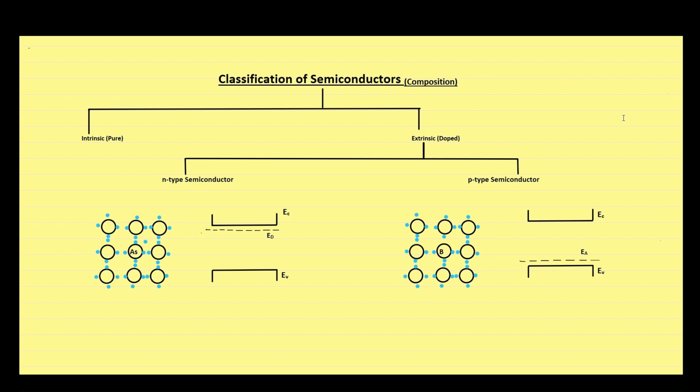Impurities which have 5 valence electrons are also called pentavalent impurities. Arsenic, antimony and phosphorus are some common examples. Such impurities have excess electrons and are therefore referred to as donor or n-type impurities. When donor impurities are added to a semiconductor, allowable energy levels are introduced a very small distance below the conduction band. Now try to understand it through the energy band diagram.